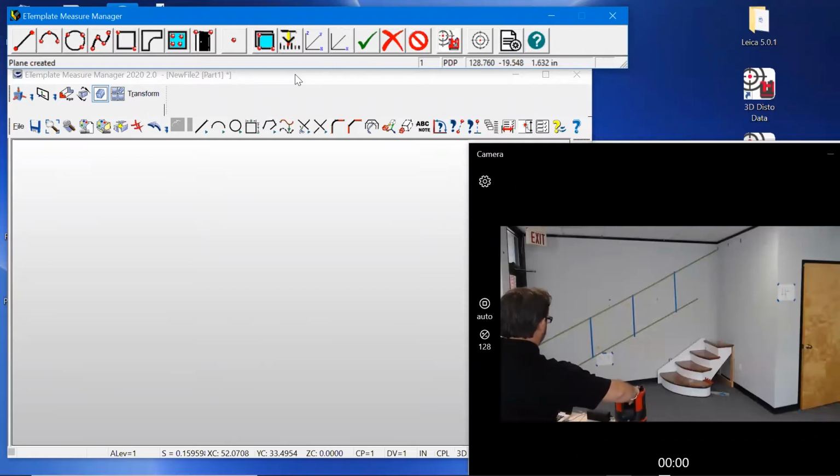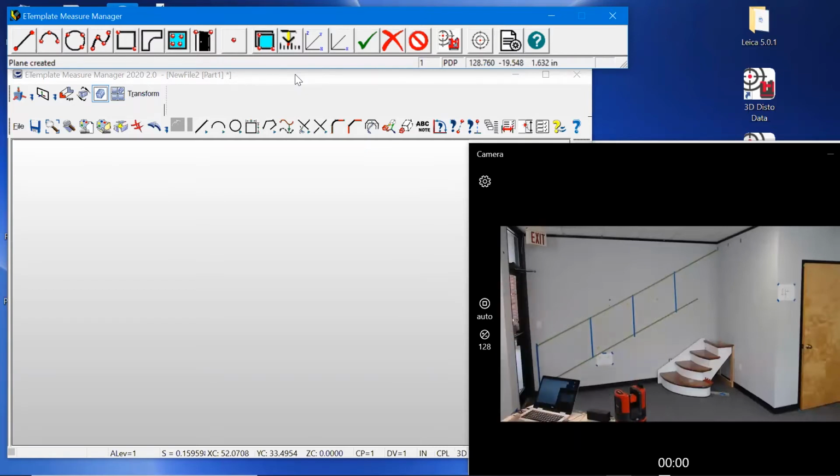Okay. Now I want to lay out my space or the adjacent walls. So I'm actually going to do a floor plan. So in this case, I'm going to take 2 points per wall and just create lines for the floor plan. Now, if you're out in stud phase in the field, you can take a point on every stud and it will allow you to draw a line based on points on the studs. If you have studs that are kicked out backwards, forwards, you can offset to either a high or a low stud if you want to do that as well. For practical purposes, we're just going to take 2 points per wall.